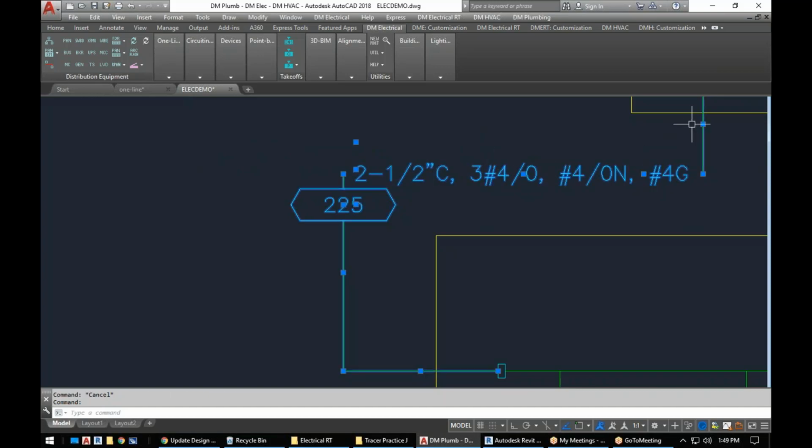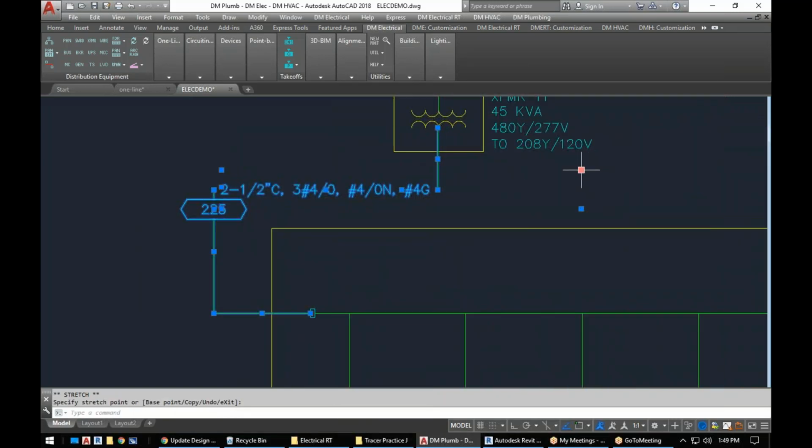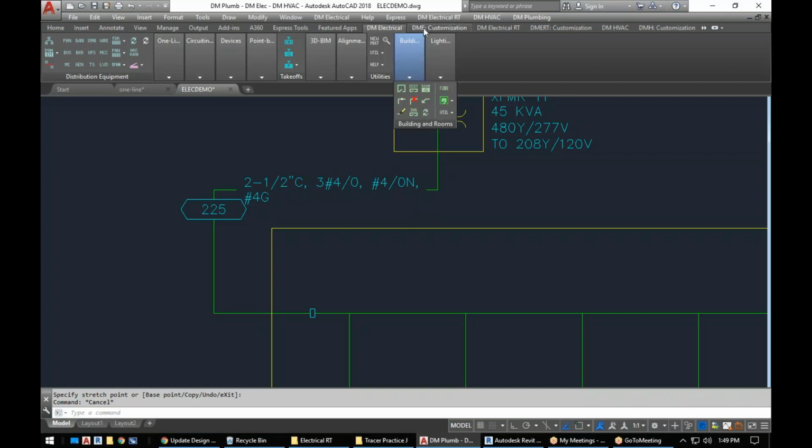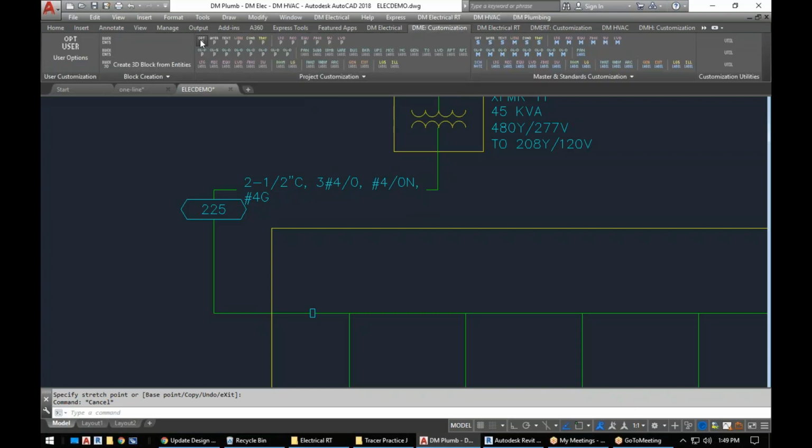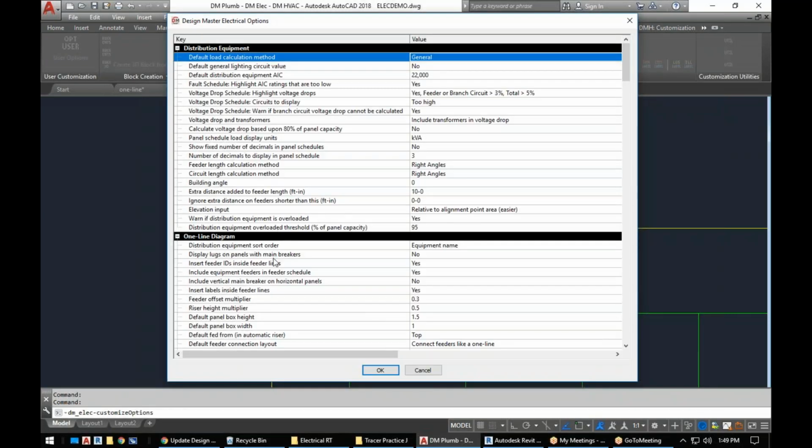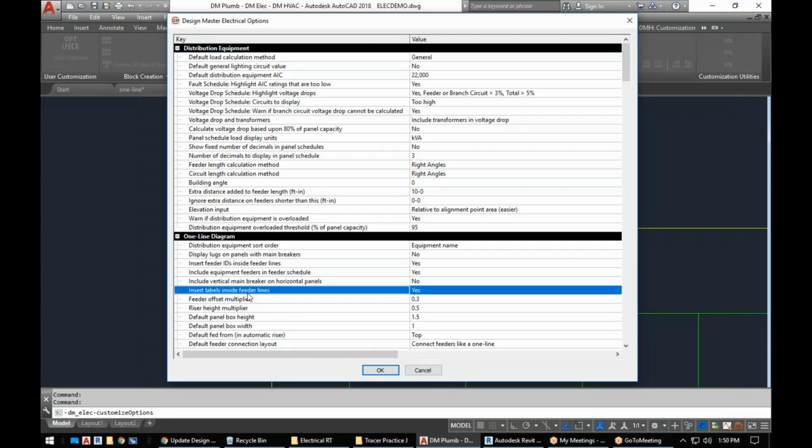That's a fairly long note, so you can't see exactly what it's doing there. Let's see, there's my grip point. Take this, we'll make it into two lines. And so there you can see it's got the break on the left and the right side. So that's the choice you have for whether your labels show up inside the line or just above and below it. That's purely your preference as to what you like that to look like.